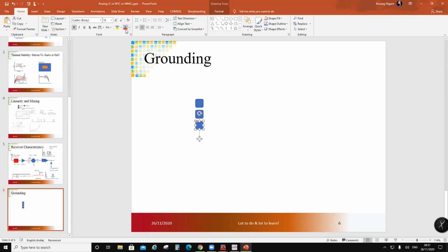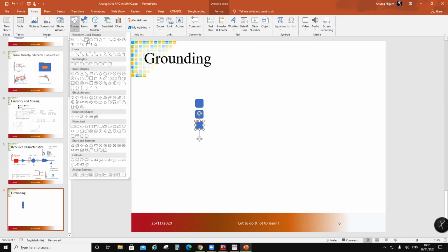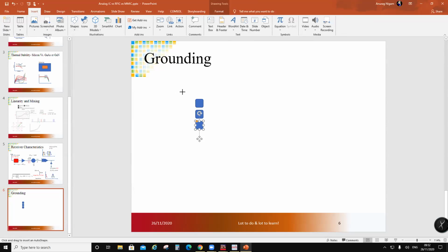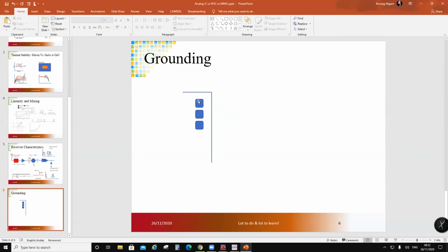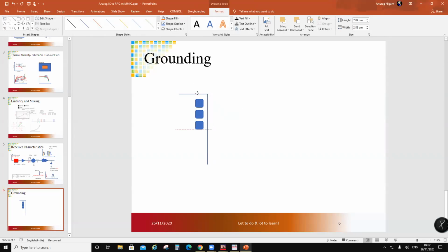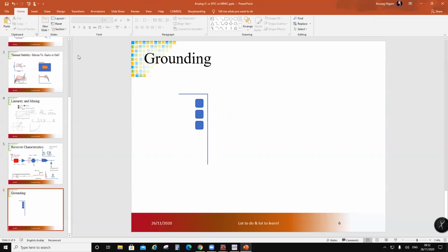Because it is a conductive substrate, right? If it is a conductive substrate, you can ground it, but that would be a very poor ground. And to bring it, the only way is the bond wires. Okay, so let's say this is the edge of the chip, and these are the pads on the chip for ground.